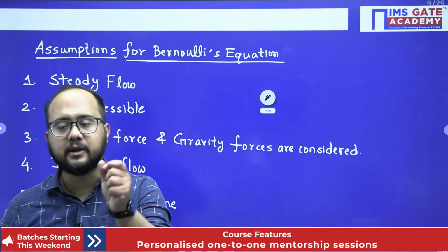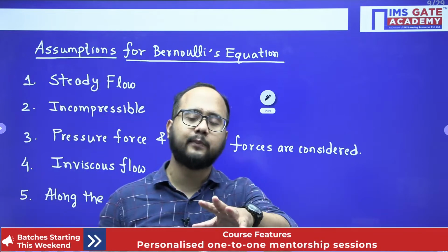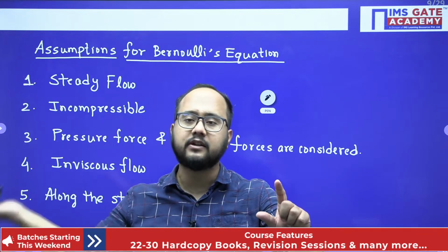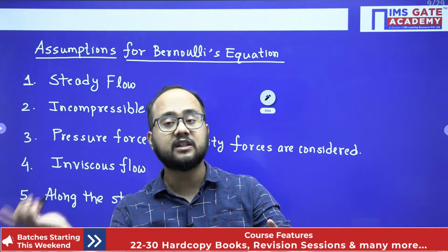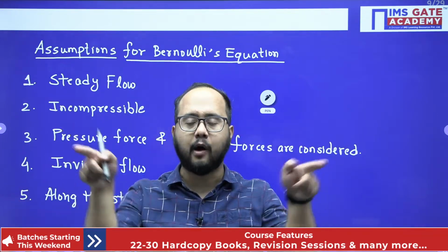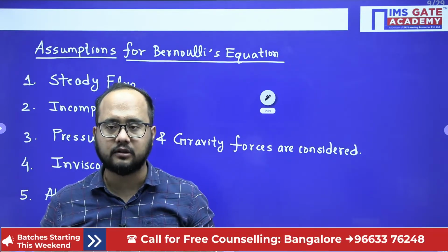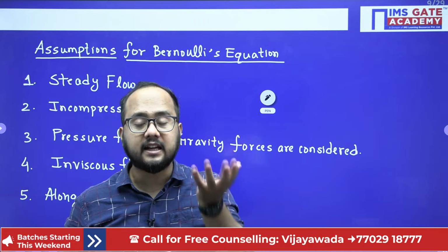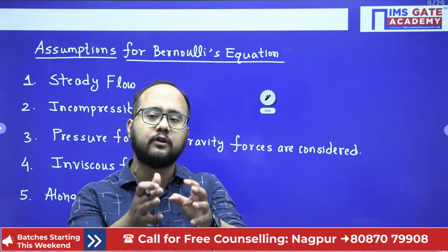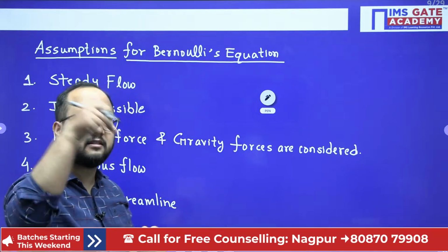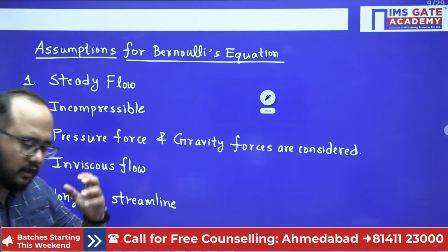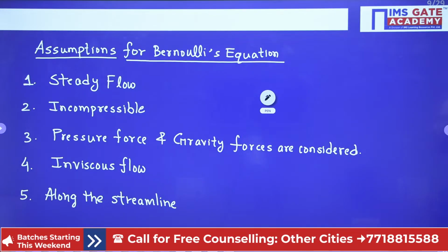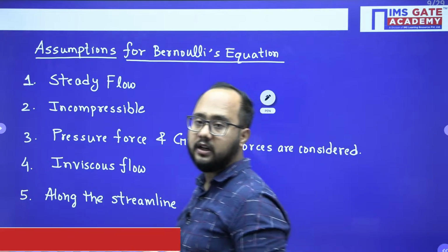From the term itself, stored form of energy is the energy within that particular fluid itself. But if I use a pump, from an external source I am giving some energy to the fluid. That is energy in transition, because it crosses the system boundary. That basic part we have discussed in thermodynamics also. So both are totally different. Energy which is stored in the fluid, within the fluid itself, that particular energy will be there. Not from an external source. That is the stored form of energy. These are the basic points that you need to understand.